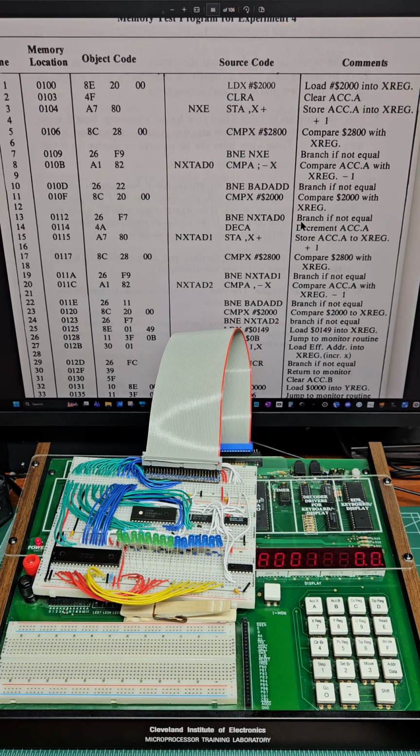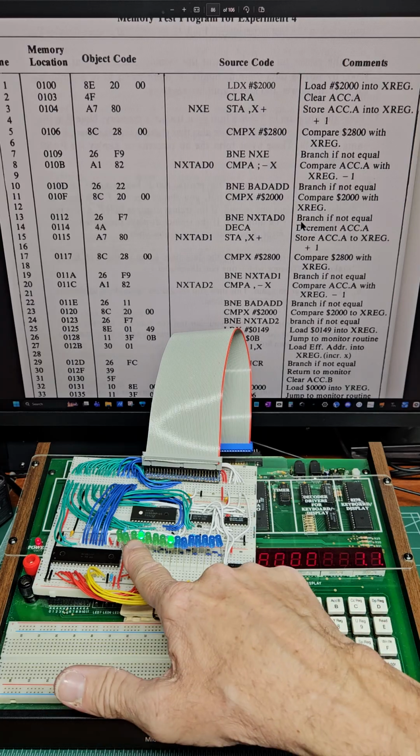And then I go to the next address, and this is the address you go to enable that and make it work. And the way you do that, type in a 04, and that 4-bit enables those registers. So now it shows it reset back to 00, but now anything I type in here will be displayed on those green LEDs. Like if I type in FF, all of them are lit, or 00, none of them are lit. Or if I want to do a 11, it shows a 11 here, it's a 11 there.